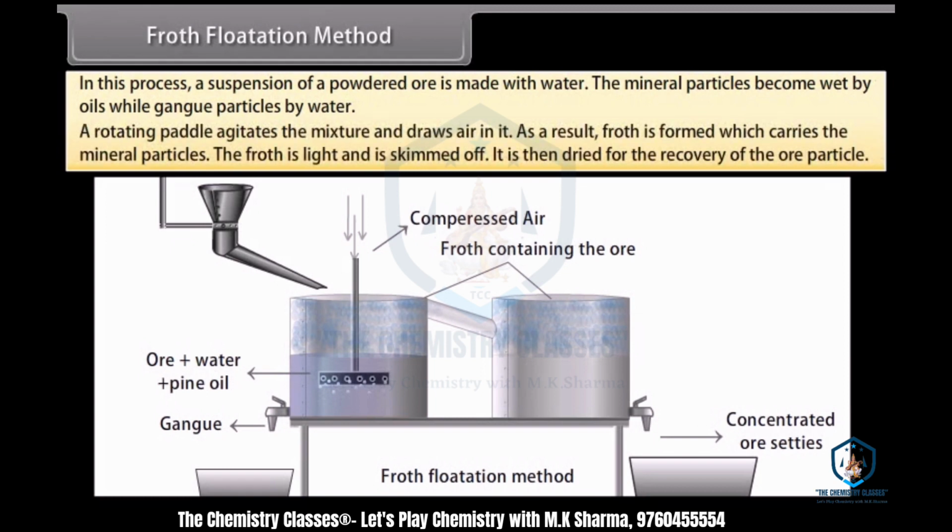A rotating paddle agitates the mixture and draws air in it. As a result, froth is formed, which carries the mineral particles. The froth is light and is skimmed off. It is then dried for the recovery of the ore particles.